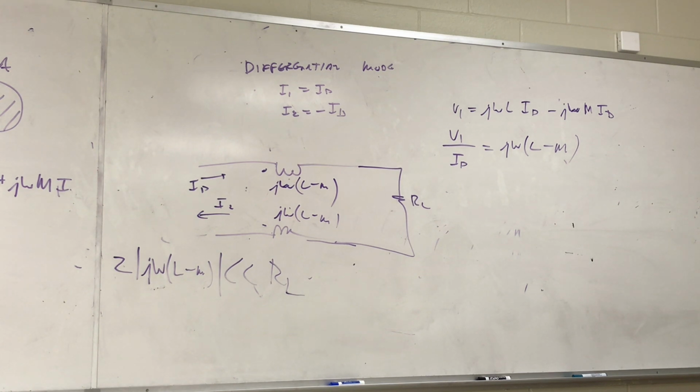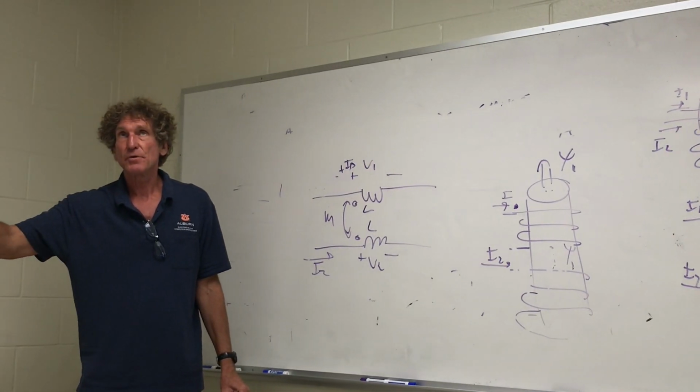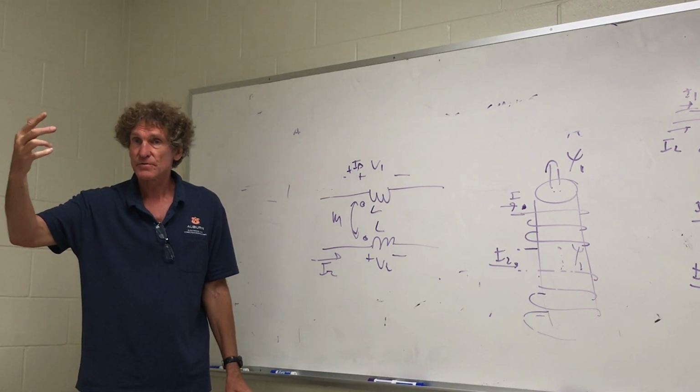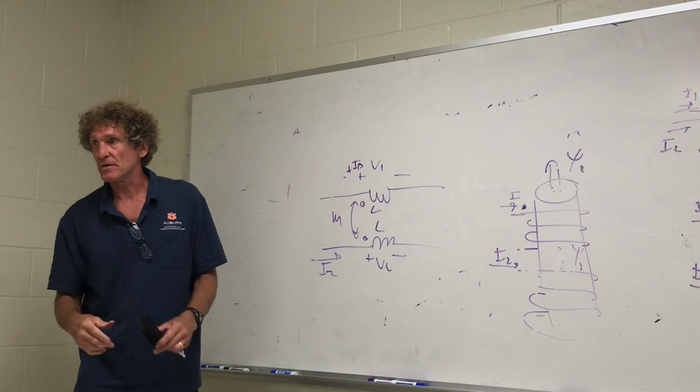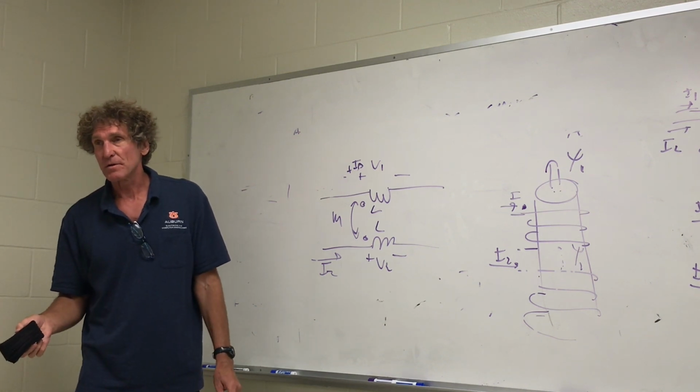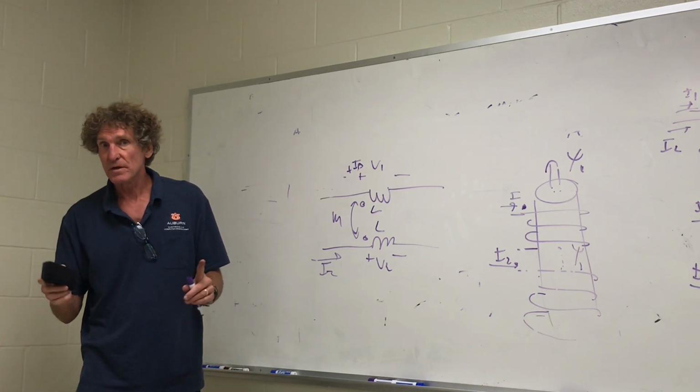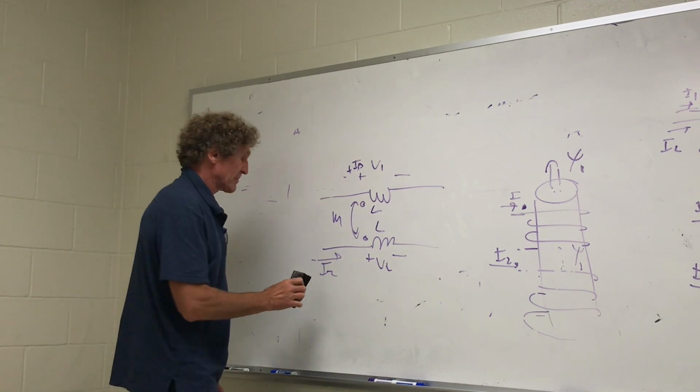If you have, especially older devices with audio amplifiers, if you have long cable in here, it's a 60 hertz hum you can hear. A common mode choke, if you put it in series, once you get past the plug level and into the input, you have to get this at the input of your devices where it goes from AC to DC after the full wave. You put that in there, it gets rid of the heartbeat. I said something here where you really probably don't appreciate it yet, but you will in time if you ever have to do this kind of stuff.